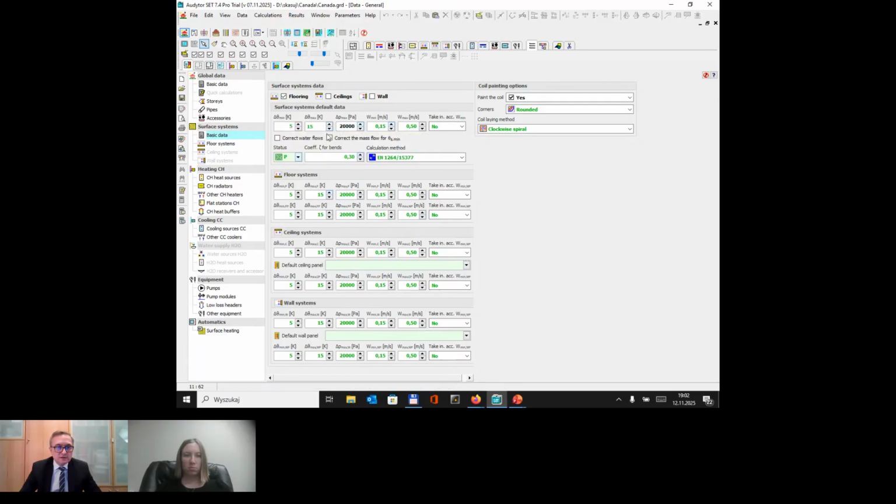On the other hand, 15 is already pretty high. And if you have a higher temperature drop than 15 degrees Celsius or Kelvins, as the temperature difference is the same, then it would mean the opposite. The flow would be very low. So, okay, low flow, low energy costs. However, such very low flows could be very hard to control. So the system won't be that stable.